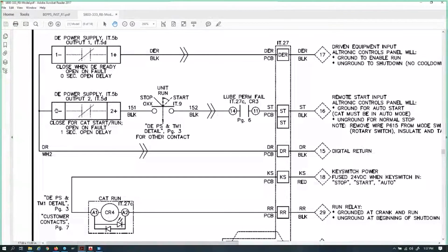So right there, without knowing much about this system, I know, because remember these are polarity sensitive, solid state output modules / relays, and don't ever call them relays though, that this is a ground. That's a ground coming into this side, and this side is a load.